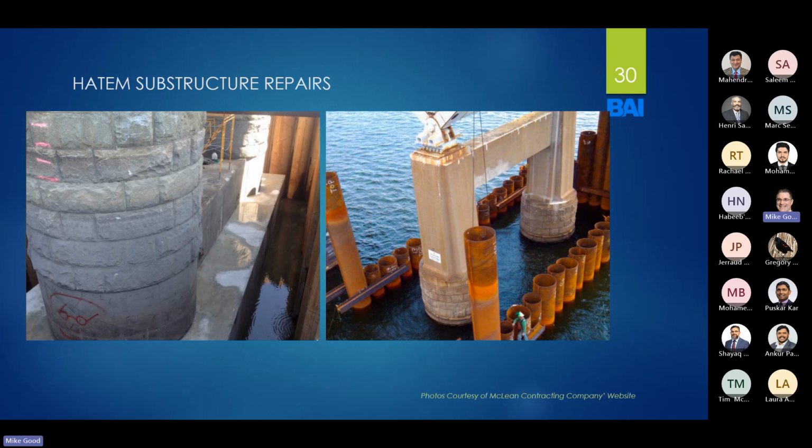Next problem, sheet piling was not strong enough to stand up on its own if that soil washed away. So we had to come up with a new method for creating this cofferdam. And we looked at a number of different things, secant pile walls, concrete sheeting, and all kinds of stuff, and we couldn't find something that worked.